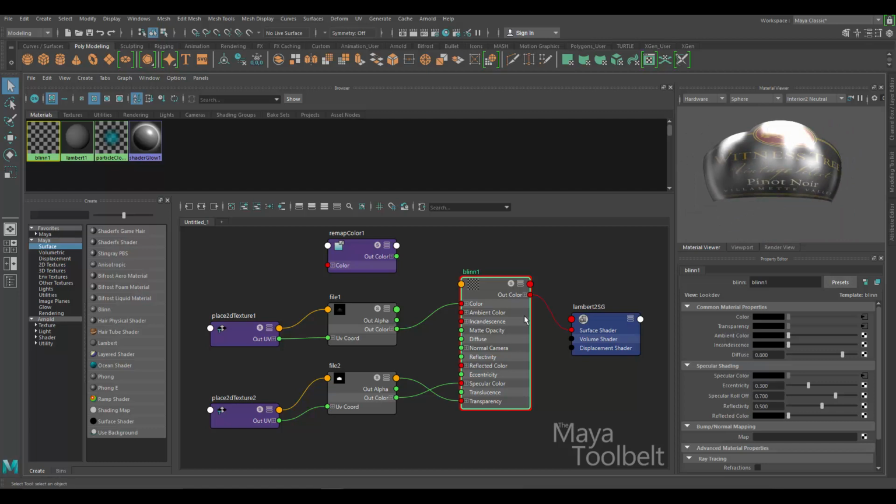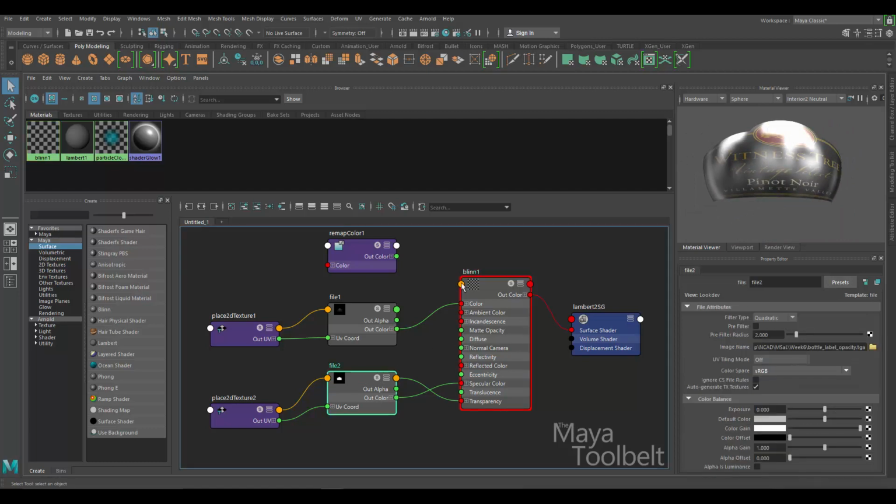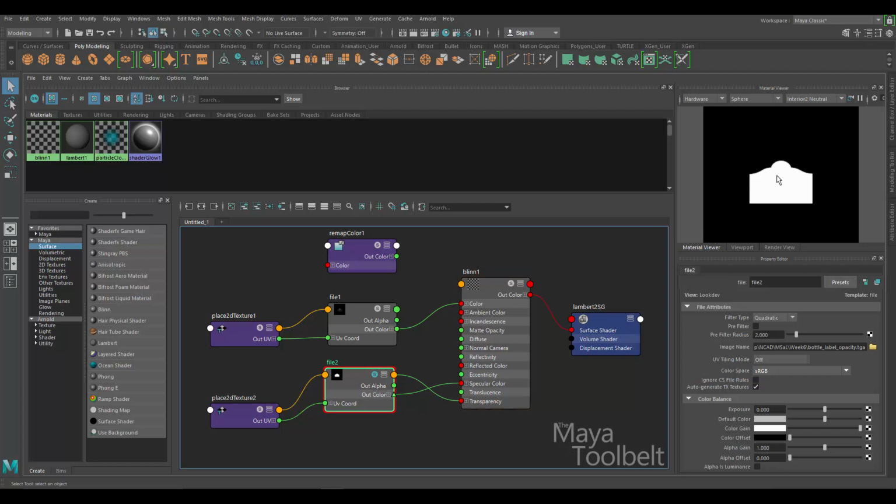but I didn't want it to be that shiny, okay? But because my texture is being used for multiple things, it's being used as a transparency mask, which requires the texture to have a full white value here. If this value was more of a gray tone, then that means the label would be semi-transparent. It wouldn't be completely opaque because it wouldn't be completely white. Okay, only a completely white value is opaque, and a completely black value is completely see-through. That's how the transparency texture works, or opacity.